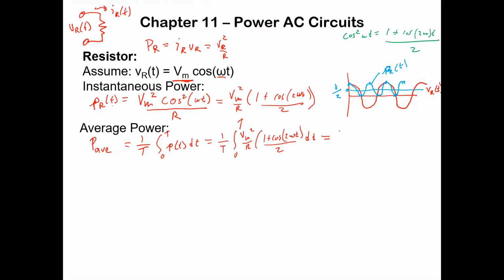And well, it turns out that the cosine has an average of 0, right? If you integrate a cosine over a whole cycle, half the time it's above 0, half the time it's below 0, and those things add up to 0. It cancels out, right? The average of a cosine is 0 over one period. Cool with that? Yeah, but you still have this raised part here. So that raised part gives you an average, right? And that actually works out to just be Vm squared over 2R.